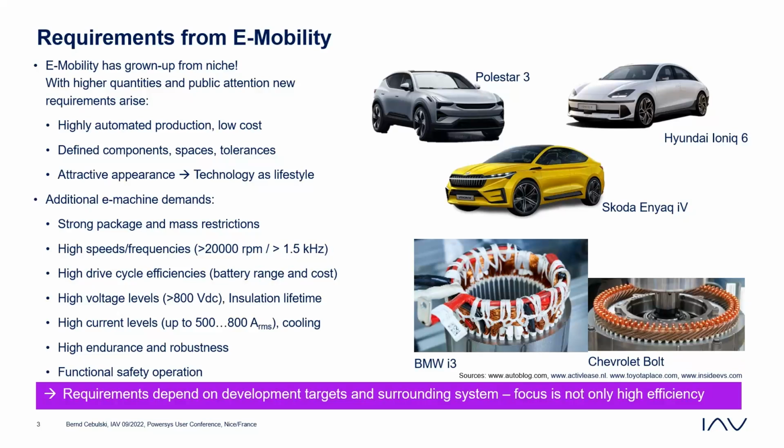And last but not least is the functional safety operation, which is my topic today. So even if it's maybe not the main task of the machine designer, we have to look at the failure reaction, especially of the three-phase short circuit, since this is the main so-called safe state of the electric machine, at least in Europe. I know there are different approaches in Japan. Yeah, and this is really putting a lot of different things on the electric motor.